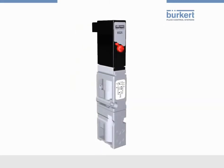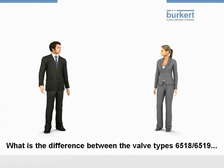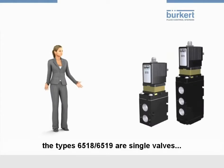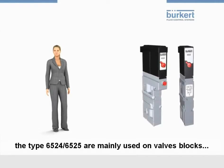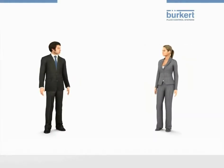Now, Tom and Lisa have prepared some questions. Lisa, I have a question for you. What's the difference between the valve type 6518 and 6519 and the type 6524 and 6525? The types 6518 and 6519 are single valves that are often mounted directly on the actuator. The type 6524 and 6525 are mainly used on valve blocks and valve islands due to their compact design. That's correct.